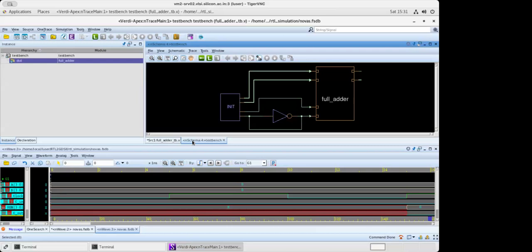At that time, compilation is not going to happen. Like when we were running the first command VCS, it will give you the error, file not found, or syntax is incorrect. You have to fix that as part of your RTL. So now let's go to the next stage, which is how you're going to synthesize it. Close this window, and then we will go to the next stage.